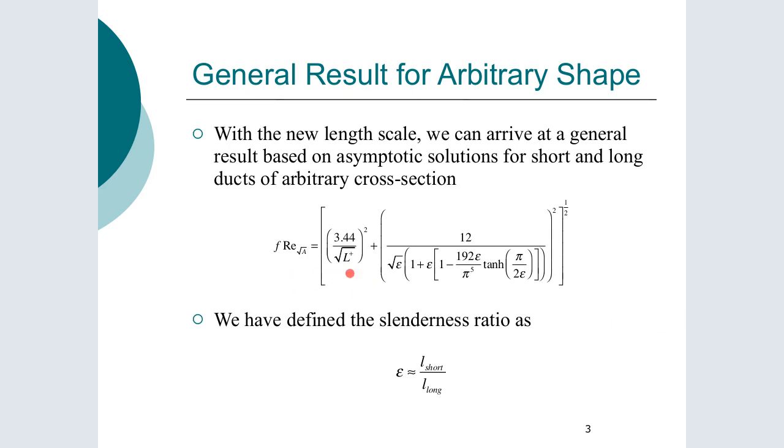And again, typically in the stuff you would have covered in fluids already, we tend not to consider the pressure drop due to the entrance region or where the flow is becoming developed. In microchannels, depending on the flow rate, you don't know whether that is important. And very often we have quite small conduits interface with longer ones, and there may be a pressure drop contribution that is dominated by this term in some portions of the device and this term by other portions, or a combination of both. So this is a general equation that lets us do some design calculations without going to the brute force of CFD.